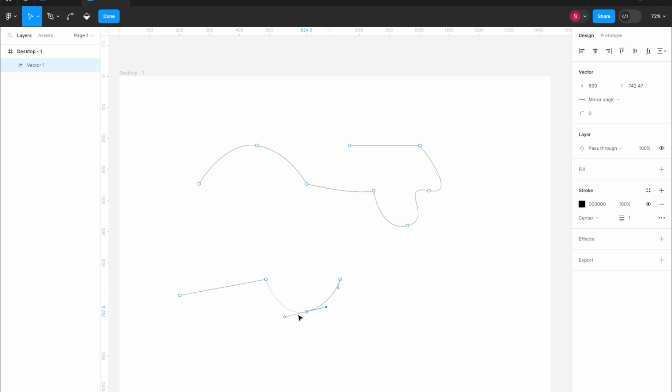We can have two types of point, though. Soft points: the handles work like a balance, equal and opposite in terms of inclination, and in this mode, we can draw curvilinear or S-shaped segments, while corner points have handles that work independently, so we can also delete a handle by clicking on it and pressing delete on the keyboard.